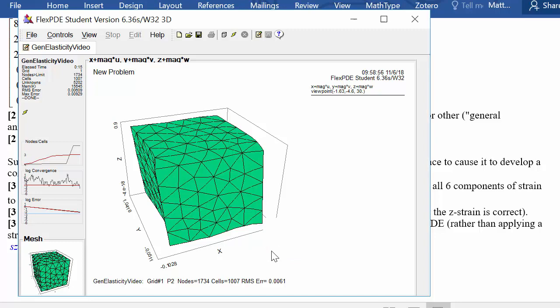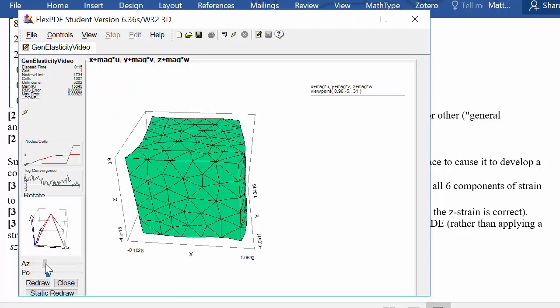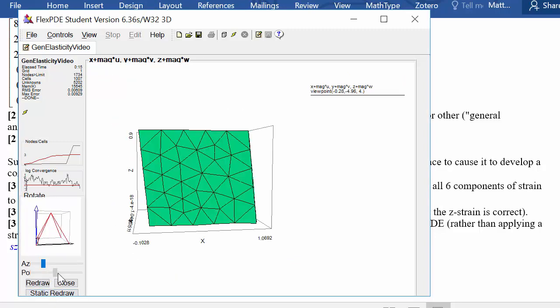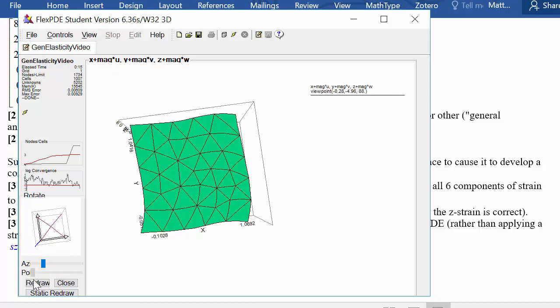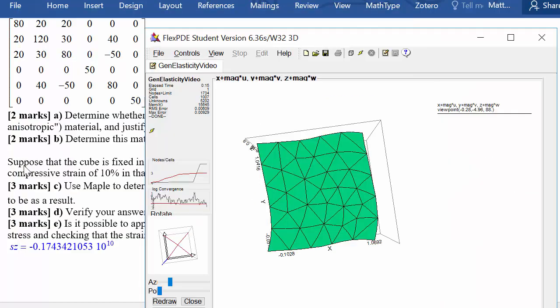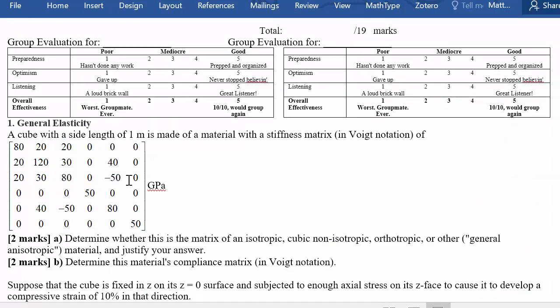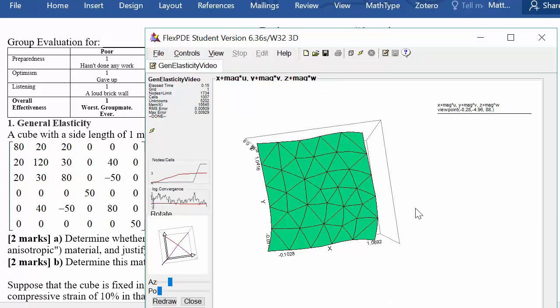So to recap, we've got some pretty strange deformations because of the properties of this particular crystal. By compressing it in Z, due to all of these components that are off axis in its matrix, we've got compressions in Z being linked to shear things showing up. So the material doesn't just stay as a rectangular prism when you end up compressing it, but can have all kinds of crazy things show up with its particular shape.